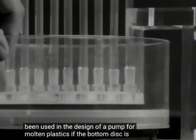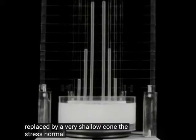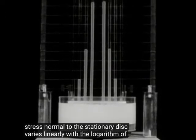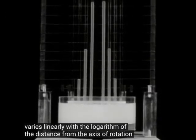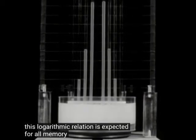If the bottom disc is replaced by a very shallow cone, the stress normal to the stationary disc varies linearly with the logarithm of the distance from the axis of rotation. This logarithmic relation is expected for all memory fluids.